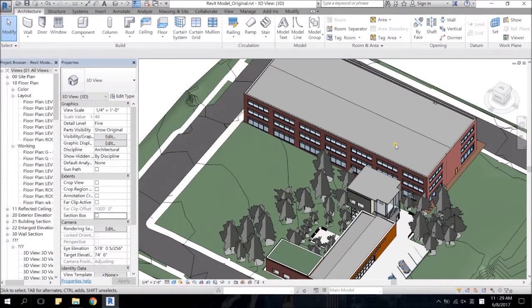In order to process the daylighting analysis, the very first thing that we have to do is to simplify the model. The reason for us to do that is because, as we all know, the Revit program is able to create the building component into very detail. However, the detailed model that being imported into Rhinoceros will dramatically increase the required time for the process of daylighting analysis.